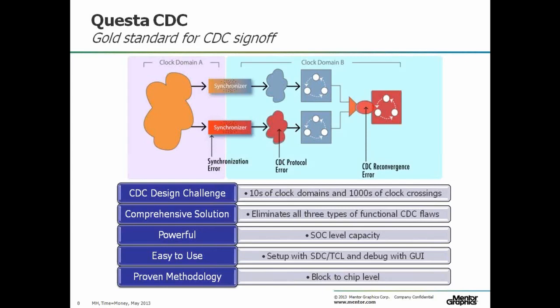And then having a synchronizer in place is just one of the problems. You need to operate the synchronizer correctly, otherwise you can get data loss in cases, and you can even get metastability in your design, even with the presence of the synchronizer. So there is an application for formal in verifying synchronizer protocol. And then finally, there's something we class as reconvergence. So this is an area where you may have logic that's in the fan-out, some reconvergent paths, the output of synchronizers. You can get variable delay through synchronizers. So if the convergent point and the convergent logic has made some assumptions about the data out of the synchronizers and their timing relationships, then you can be screwed unless you fully check for reconvergence paths. So you may get variable delay through one and not the other.